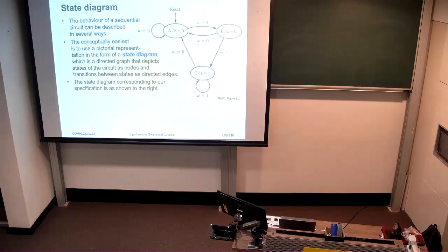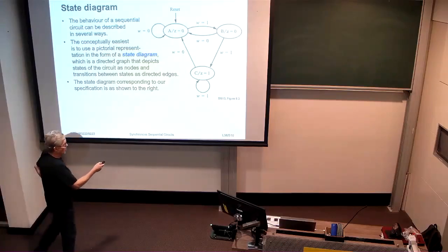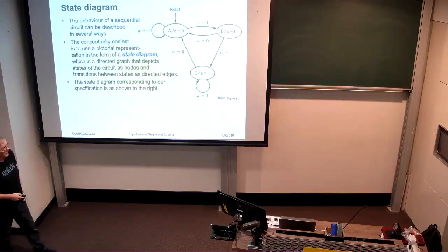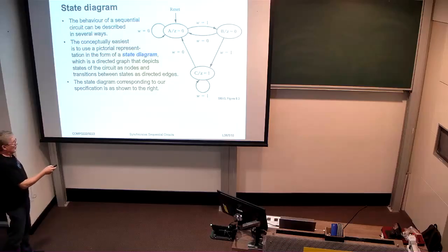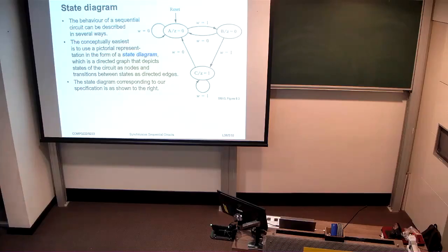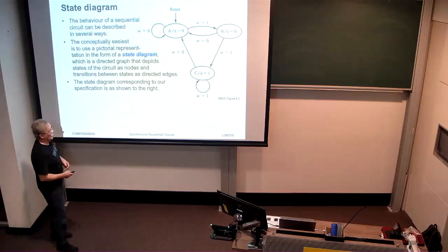So this is our state C, where that fact is now known, and therefore our output should go to 1 in state C. We also determined that if we get another 1 in state C, then we should stay in state C because it's still true that the preceding two clock cycles had a 1 as an input. On the other hand, if we see a 0 in state C, we return to state A. So that's the state diagram that we would have derived if we'd gone through this analysis and built the behavioral description of the circuit as we went along.